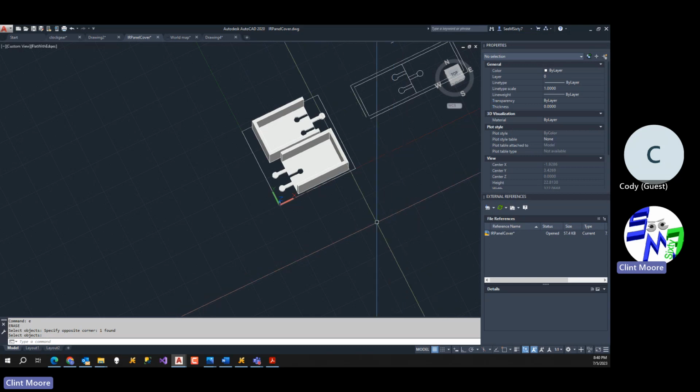Something else that comes up while you're doing your 3D prints is that most 3D printers, and slicers typically, work off of millimeters and not inches. I drew all this in inches. So when I bring it over into the slicer, the Prusa slicer, I had to actually scale it up in the slicer by 2,540%. Okay, because there are 25.4 millimeters in an inch. So that's kind of how you end up doing that.